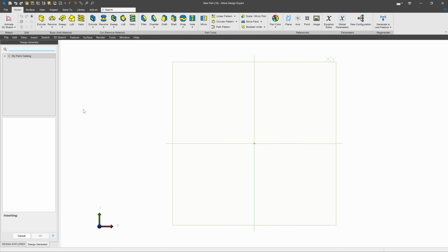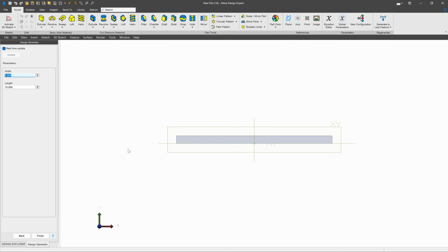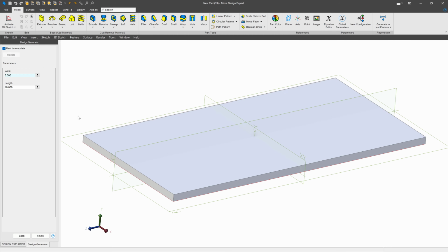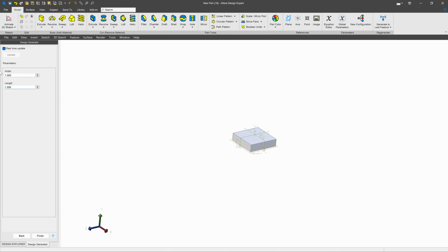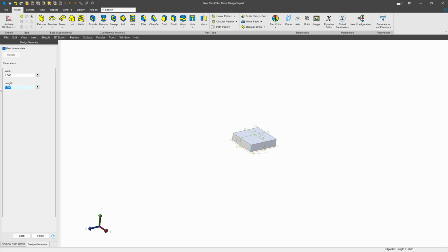And we'll test some of these values and rules that we made. I'll go to my catalog, sample parts, and click on my latest. From here, if my width is 1 and my length is 1, then we have a thickness of 0.25. If my length goes to 3.5, we now have a thickness of 0.5.